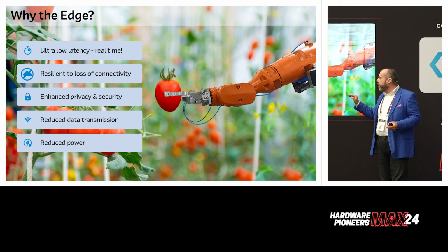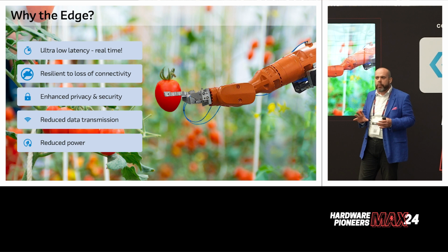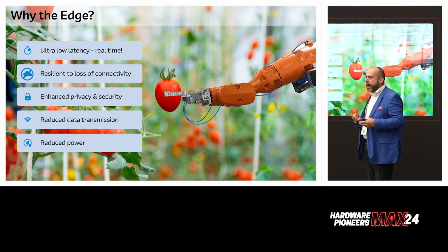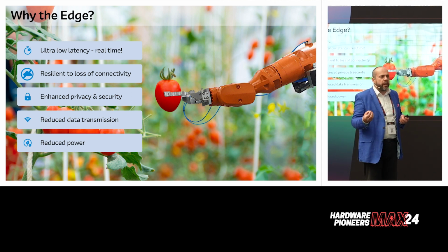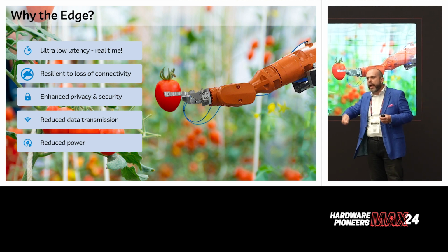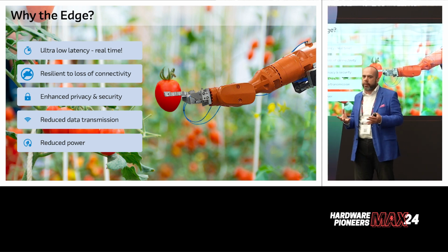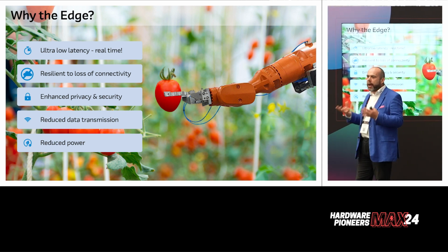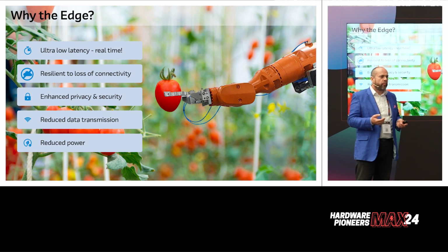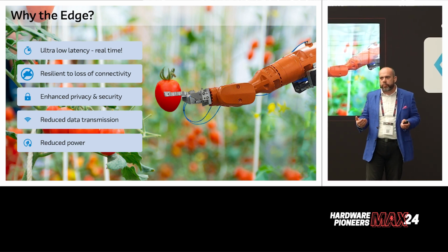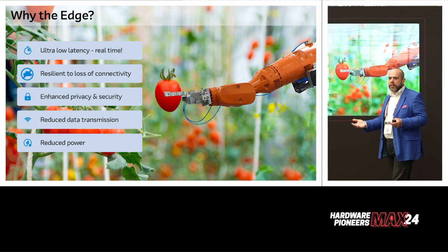Comes down to reduced data transmission, and actually reduced data transmission and reduced power I'll speak to at the same time. So if you think about a generic device that has some sort of AI and it also has a radio, and by radio, I mean that could be Bluetooth, it could be Wi-Fi. I'm not necessarily talking about your traditional AM radio, but you've got a transmitter in there. Roughly, on most designs, 70 to 80% of the power used by that design is by its radio. And so if you can reduce the amount of time you have to transmit, then your device will last longer.